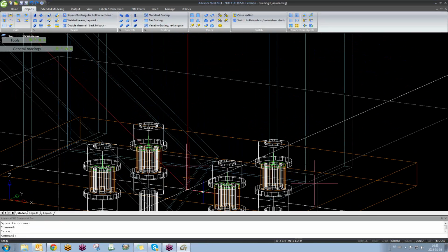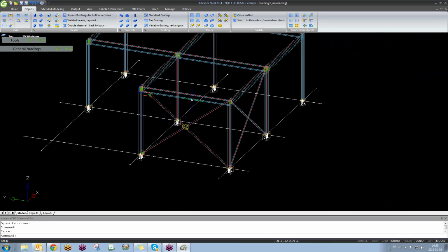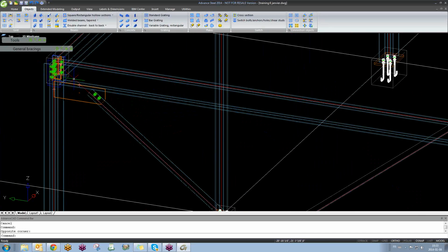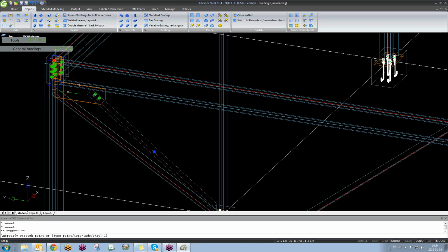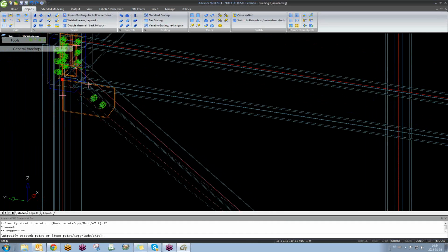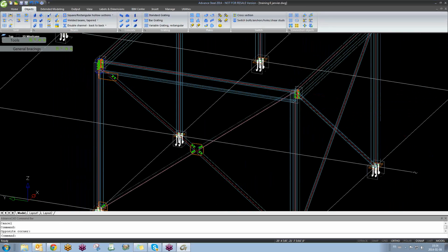In a situation like that, that's the only way you know that those two intersections are connected, by zooming in and looking at it. So if you try to apply a connection and it's not quite on there, will it not make the connection? It will, for the bracings, because sometimes the work point isn't exactly here. If I put it down by 1 foot, it will adapt. Do you see it here? It will just adapt the connection. If I put it up 6 inches, it will adapt. Okay. So let's say that work point was going to the center of that beam, then I could just come down whatever the distance is of that beam depth. Yeah. Okay.